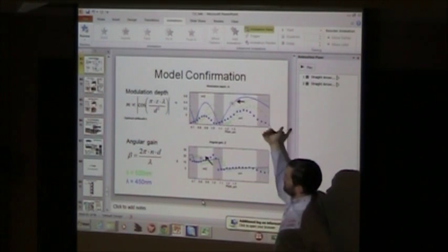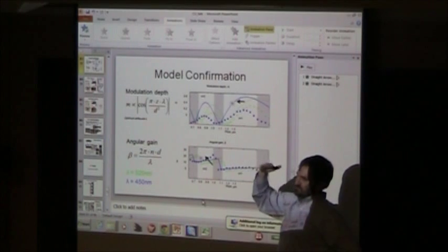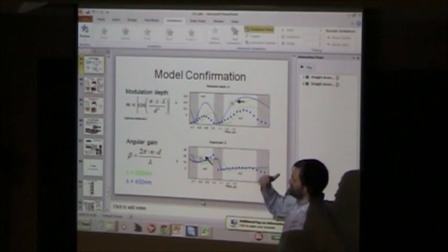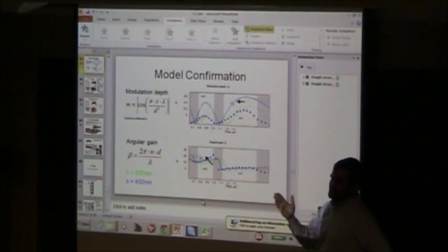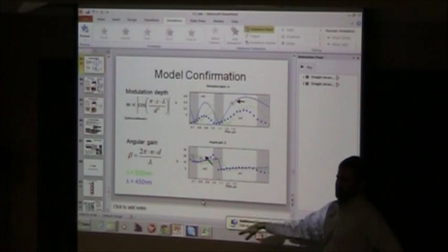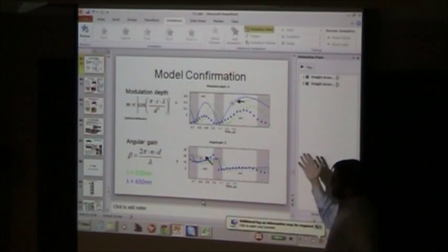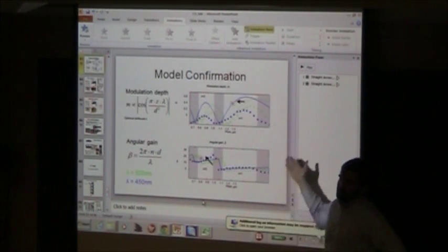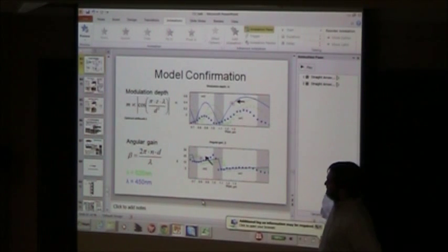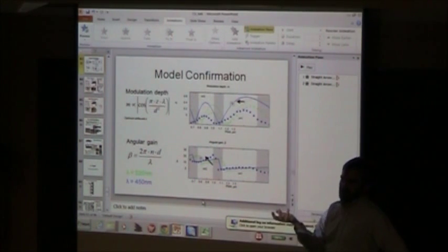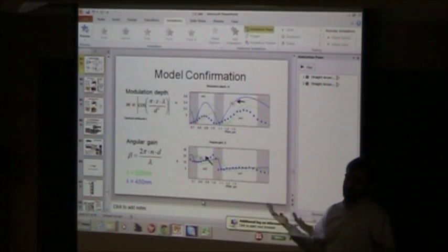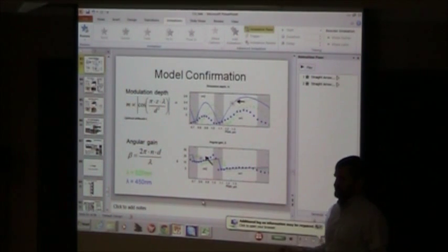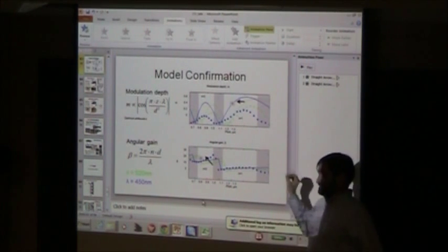So we found in general, as we typically use low order Talbot depths, either the first half order or the first order, we can get a single pixel to cover kind of blue through orange, if you will, with reasonable performance, and red just the size. All the pictures I showed you were actually with white light. The reason that works is that the photodiodes are also a bit green optimized. They're N-wells, about a micron deep, so they do best with green light. So we show them white, and they are effectively responding to sort of cyan or yellow, and it works pretty well. But this is a weakness of the design.